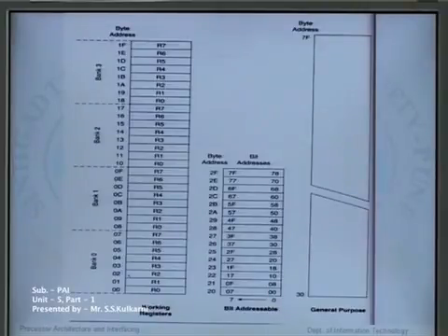The second part of the RAM is the bit/byte addressable area. It is in the range from 20H to 2FH. A bit addressable area of 16 bytes occupies RAM byte addresses in this address range, forming a total of 128 addressable bits. An addressable bit may be specified by its bit address of 00H to 7FH, or 8 bits may form any byte address from 20H to 2FH.